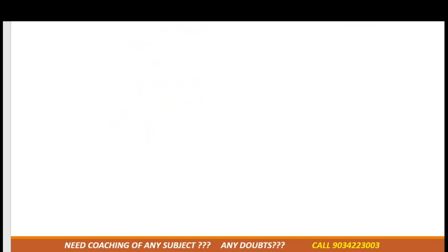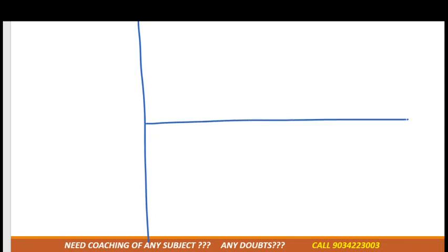Now we'll need to draw the graph. On this graph, on the x-axis, we'll draw frequency. Now we have to draw the graph for the XL. As you know, the XL formula is omega L, or we can write XL is equal to 2 pi FL.